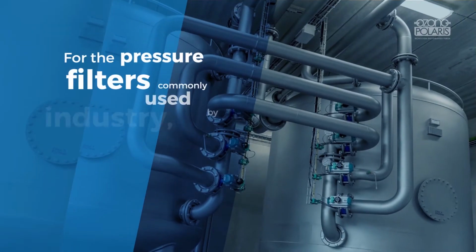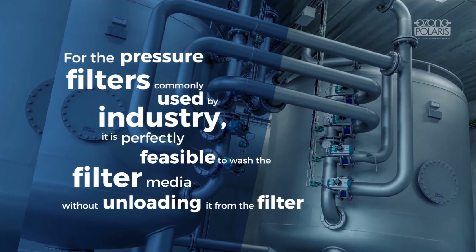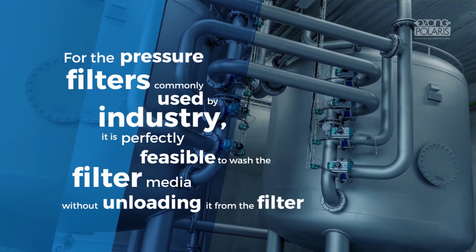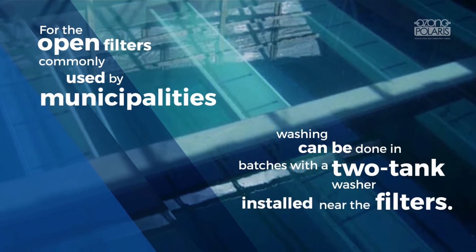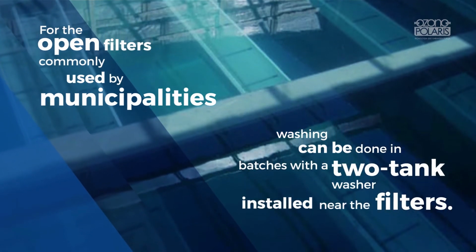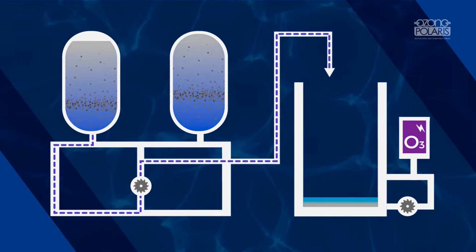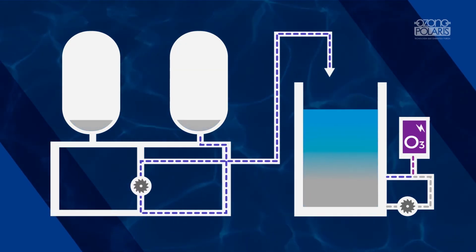For the pressure filters commonly used by industry, it is perfectly feasible to wash the filter media without unloading it from the filter, daily if necessary to keep bacterial growth under control. For the open filters commonly used by municipalities, washing can be done in batches with a 2-tank washer installed near the filters. This would be done with a frequency like that normally used for changing the carbon. The back and forth washing process generates a minimum amount of dirty water, which facilitates its treatment and disposal.